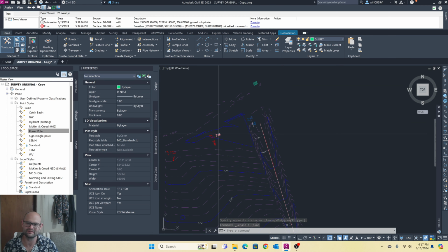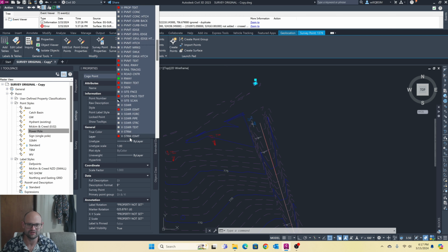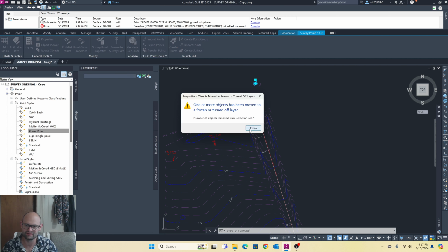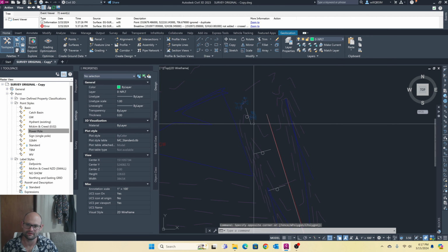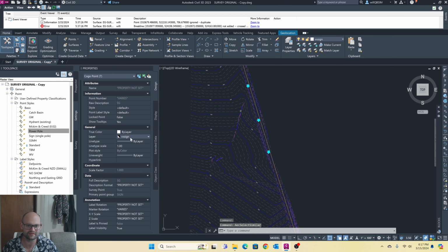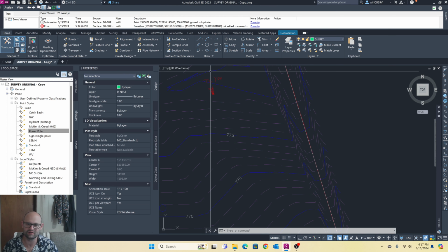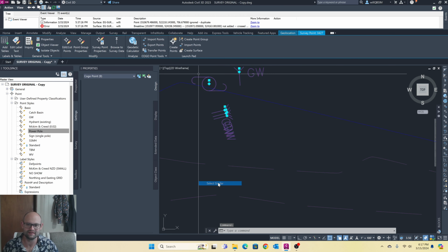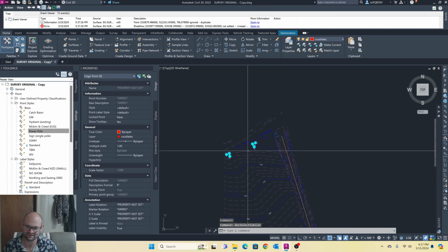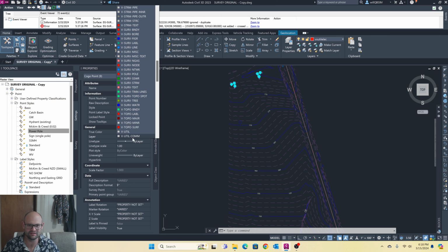So now that we know these are safely nested blocks, I'm going to move all of these to their correct layer now. So the storm structure for that catch basin. We got these signs here. We grab them all with a select similar. B sign. Let's get these power poles and the guy wires. Cool, it grouped them together. I want them on the same layer anyway. V util electric overhead.